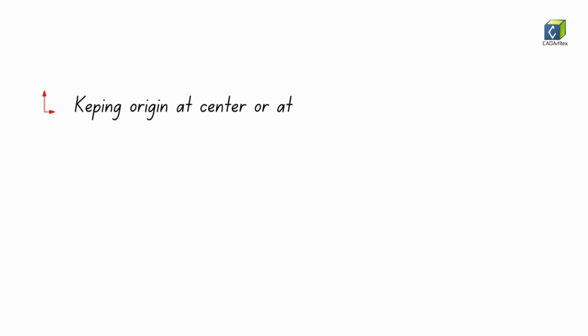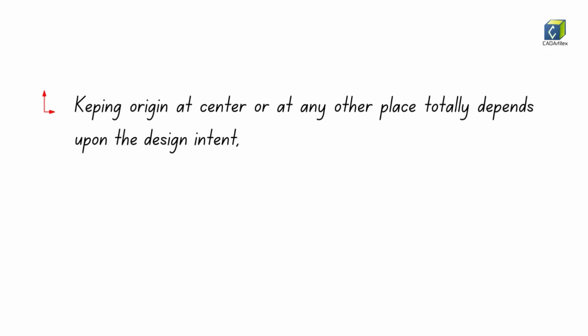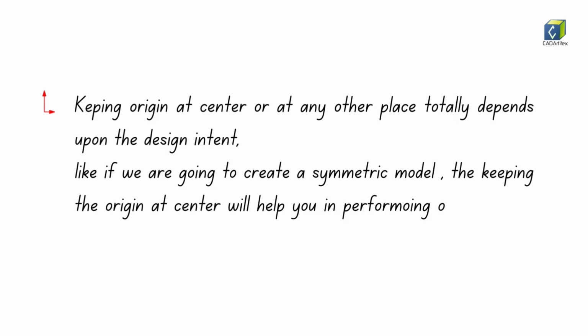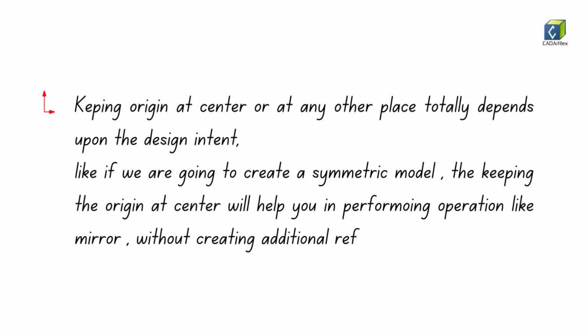Now, coming back to our question, again, keeping the origin at the center or at any place totally depends upon the design intent. Like if we are going to create a symmetric model, keeping the origin at the center will help you in performing operations like mirror without creating an additional reference plane.